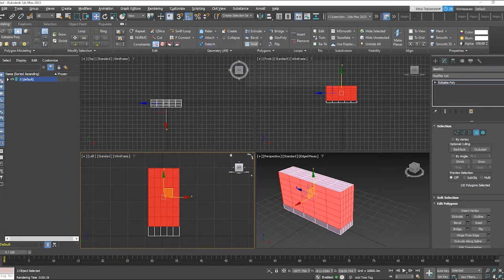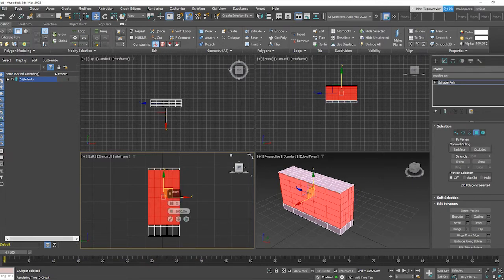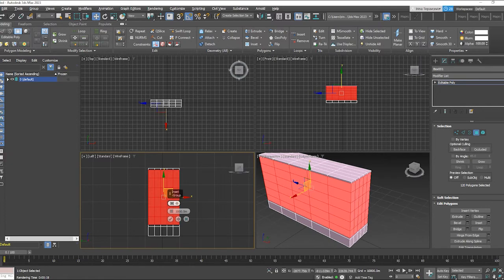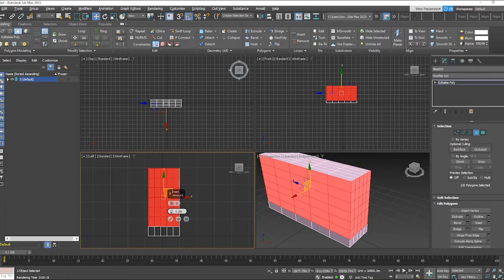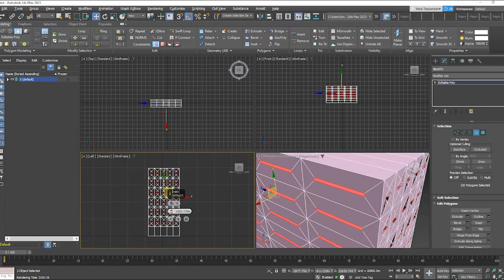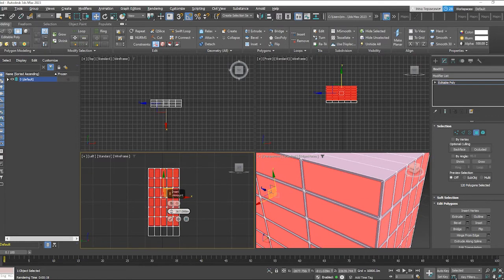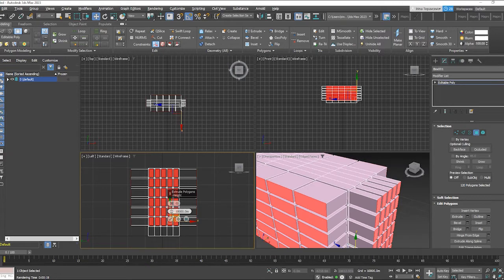With that, we want to press shift and insert, and then change group to polygon just by selecting the down arrow. And this, you can now change how much width you want these windows to look like. And then once you're fine with it, you want to select the tick down below, and then up towards extrude you select shift and click it as well.